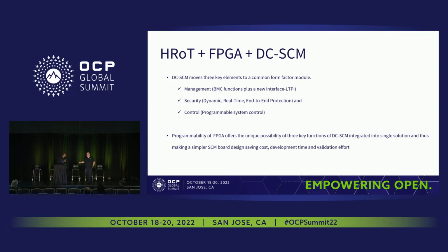One other thing. Also on the DCSCM card, as Munir's talking about, there is a security module, and in many designs today it is an add-on module going on the card, and the pinout of that additional add-on module is not defined in the DCSCM specification. So if we can work together as a community to drive a commonality of that connector, we can get a lot of advantages that we'll talk about in a moment. Right. Thank you, Jake.